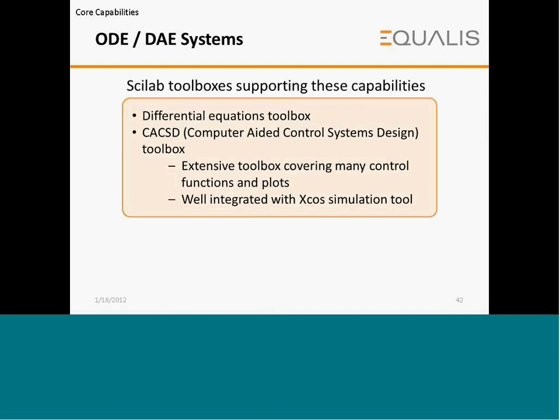For ordinary differential equations and differential algebraic equations, Scilab toolboxes consist of the differential equations toolbox and the computer-aided control systems design toolbox, that is CACSD. CACSD is an extensive toolbox covering many control functions and plots. It is well integrated with the XCOS simulation tool.